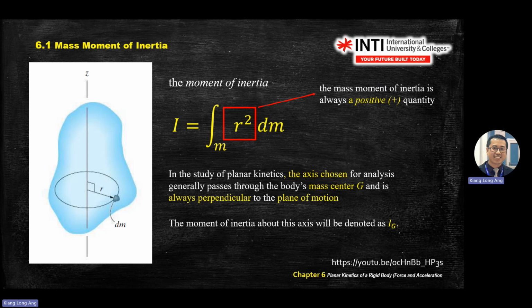Why there is a negative number is when your R goes in the opposite direction. So this is the R positive direction, which goes outside from the axis. So when the R moves into the axis, then it will become negative. Okay? But here, if you want to calculate inertia, you square it, you still get a positive number.